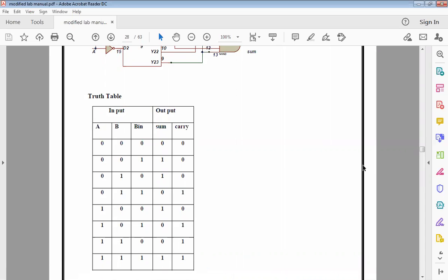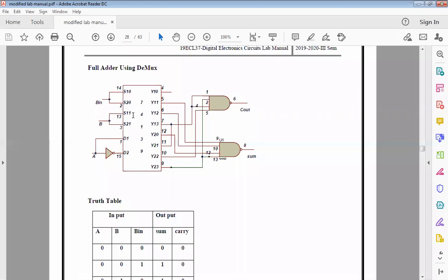No. What we do in order to implement that is use a multiplexer, because with this you can do multiple functions. So exclusively for adder and subtractor, we don't do that. We take the help of decoders, we take the help of mux because these can do multiple functions. When I have a system which can perform multiple things, then why do I have to separately fabricate them? I don't have to manufacture them separately. So I will use this one only, which can perform anything. It's like I'm coding. I first develop my truth table, and then I'm just mapping these values to my IC pins.